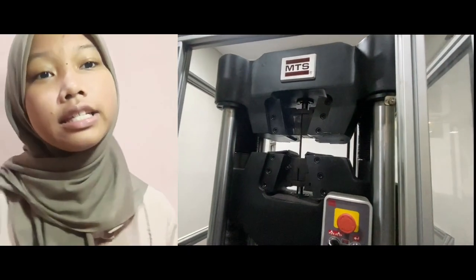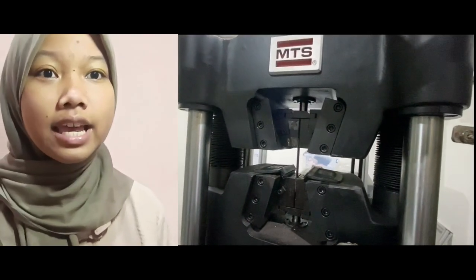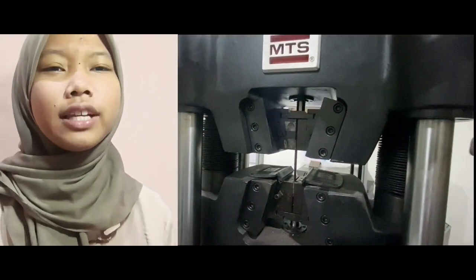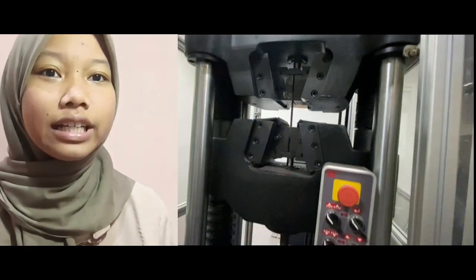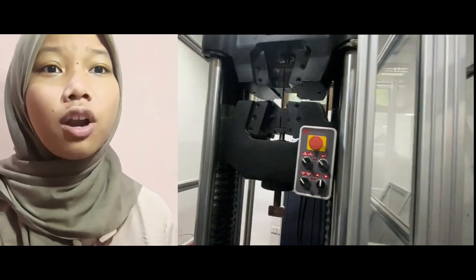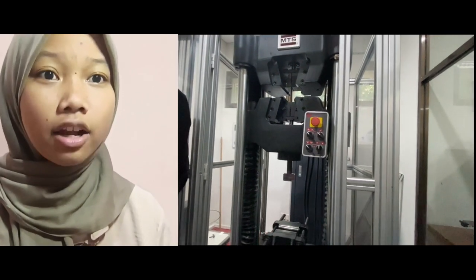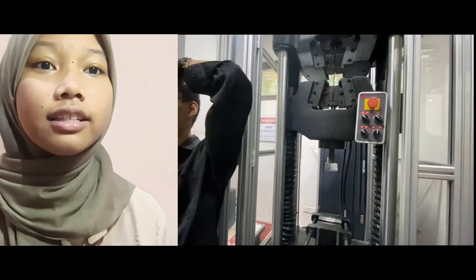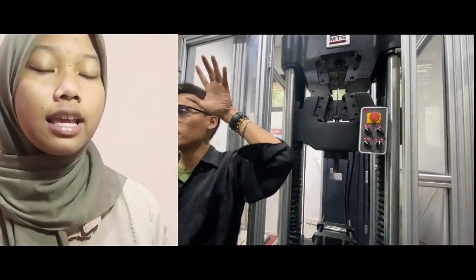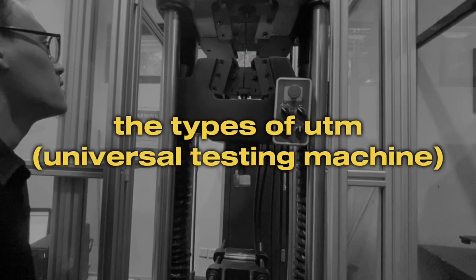The UTM is a device used to determine the mechanical properties of materials, especially tensile and compression strength. It is called universal because with different jigs or fixtures, the machine can perform not only tensile and compression tests, but also bending, shear, and other static tests. However, this machine cannot perform fatigue testing.